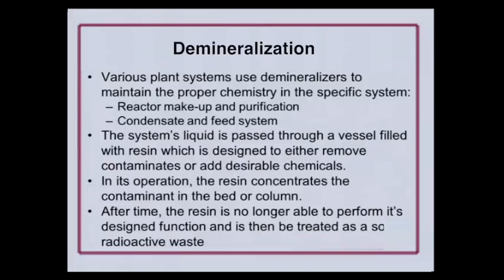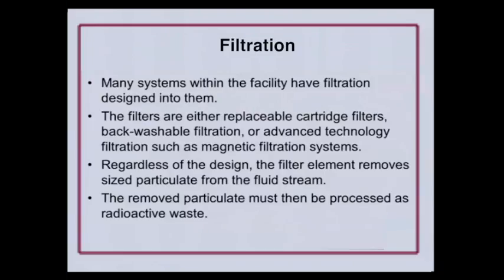Again, ultimately that resin will expend, and it will be spent and must be dispositioned. If it's radioactive, then you have radioactive resin to deal with. That radioactive resin then becomes solid waste, and solid waste can be handled through solidification, which is usually the way you handle spent resin.